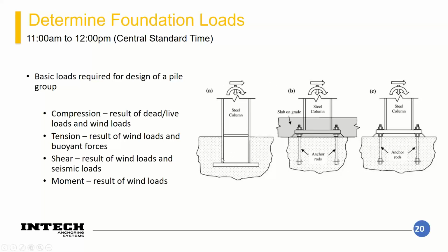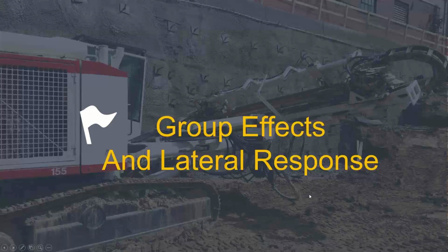So how much is this base trying to slide over? These are typically a result of your wind loads as well as seismic loads. And then you can also have bending moments that are acting at the base of these as well. And these are typically a result of wind loads. Earthquake loads typically only have a shear load that will be imparted in the foundation, but with wind loads, you'll definitely have a moment, and we'll talk about that a little bit more.